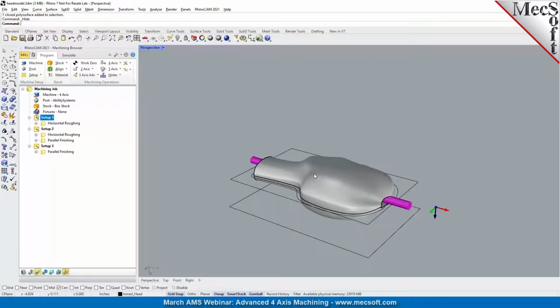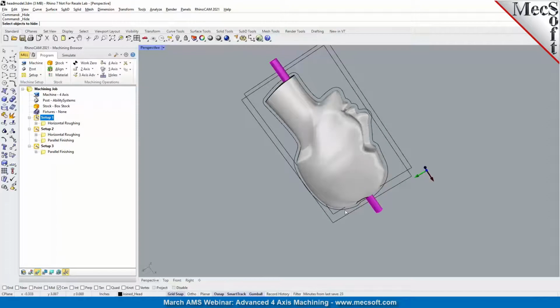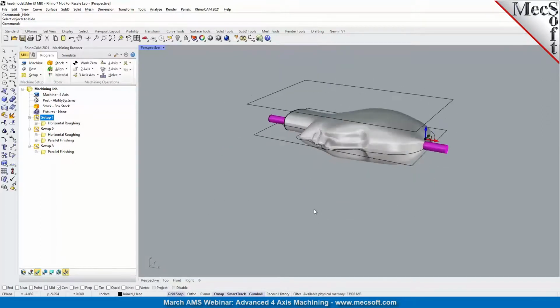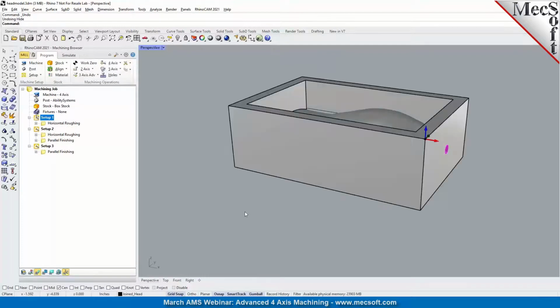Now, the benefit of doing the index machining is you just have to zero it out once at your initial orientation. And once you've done it, the rotate table setup and machining it from the other side does not require you to create multiple origins, and you don't have to go back and re-zero it multiple times. That's the beauty of programming it as indexed using your rotary table or rotary axis in here. So we will go through the steps on how to go about programming this.